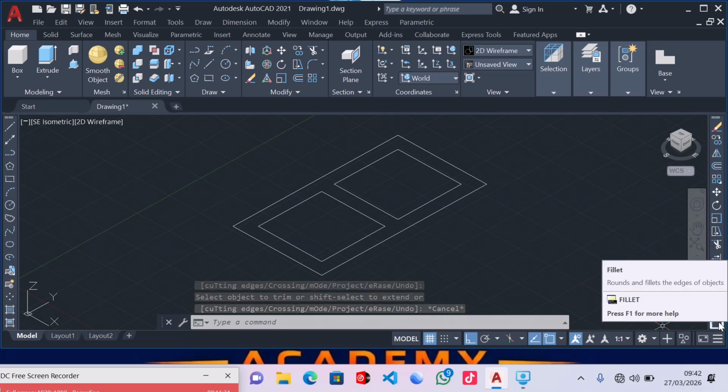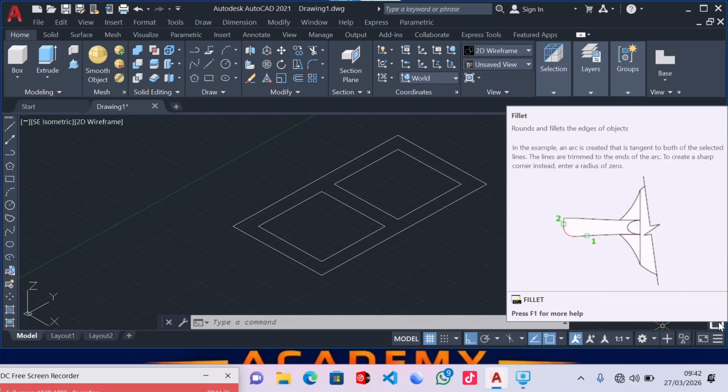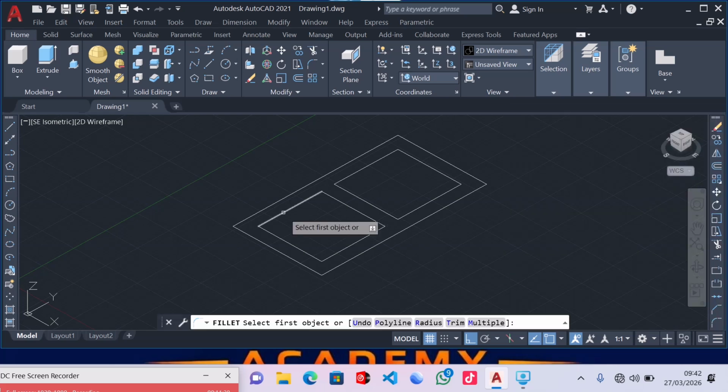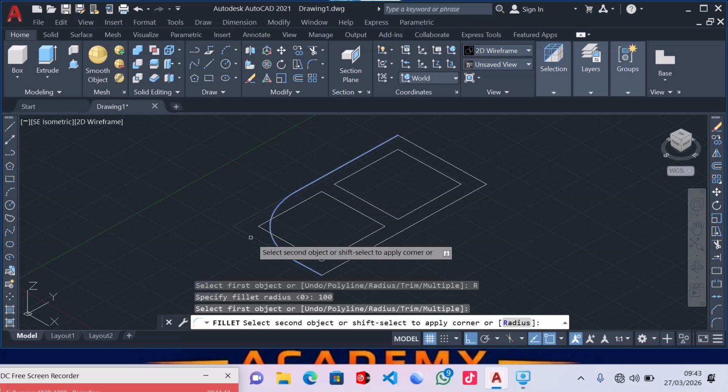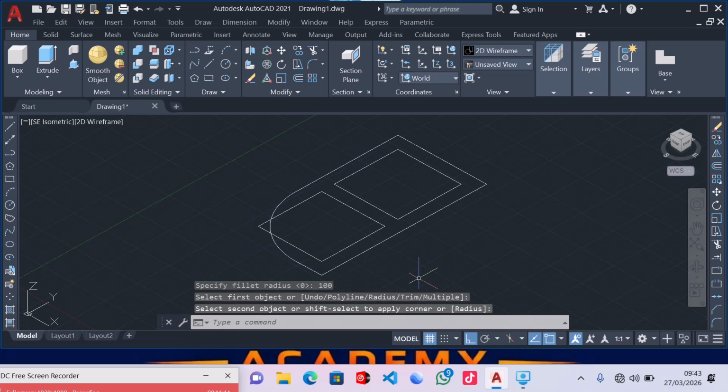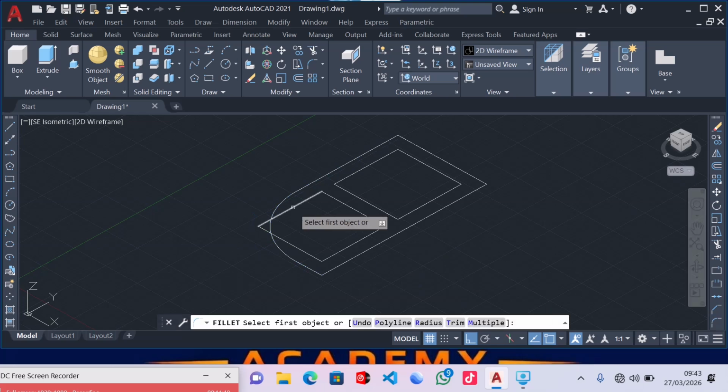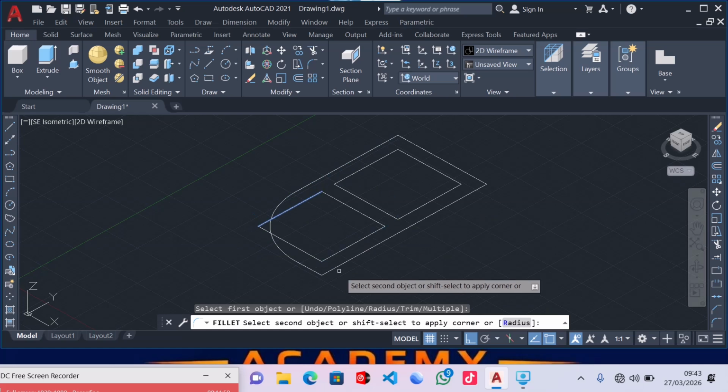They are telling me to specify the radius. So I'll come here and I click the radius. Maybe for instance, I will need the radius of around 100. So I'll click on this line. I click on this. So now I'll repeat the procedure. I told you repeating the procedure, you can click enter. If you click enter, you repeat the last command.